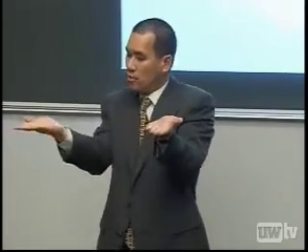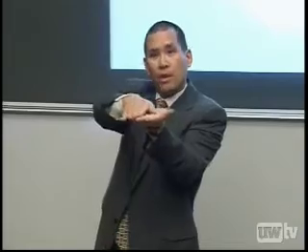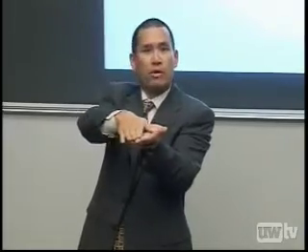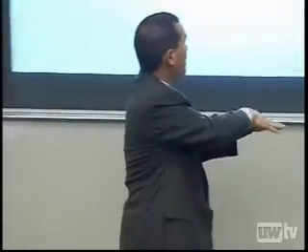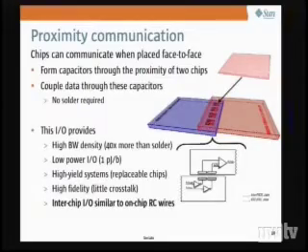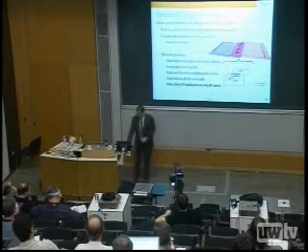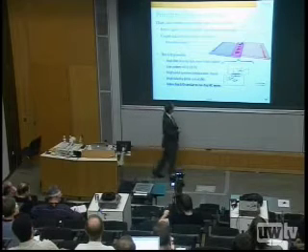On a matching chip with a matching set of squares, you put them together. You don't solder them, you don't glue them, you just put them together. And by being in close proximity, I have made capacitors. Now, if I signal on one capacitor, that's going to make the other capacitor plate move in sympathy, and I get communication, albeit at a reduced voltage, but still I can magnify that and get data across chips.